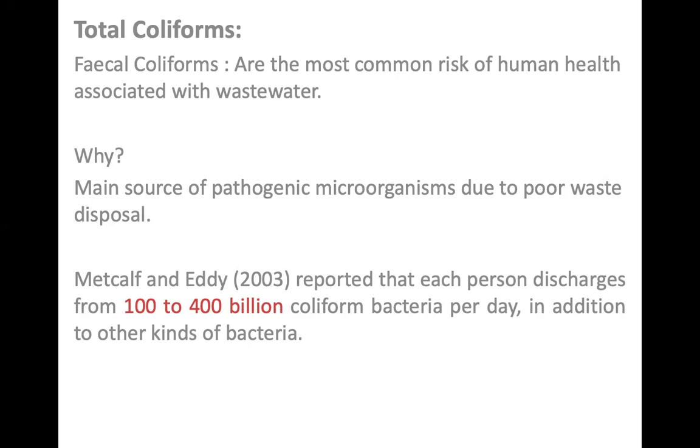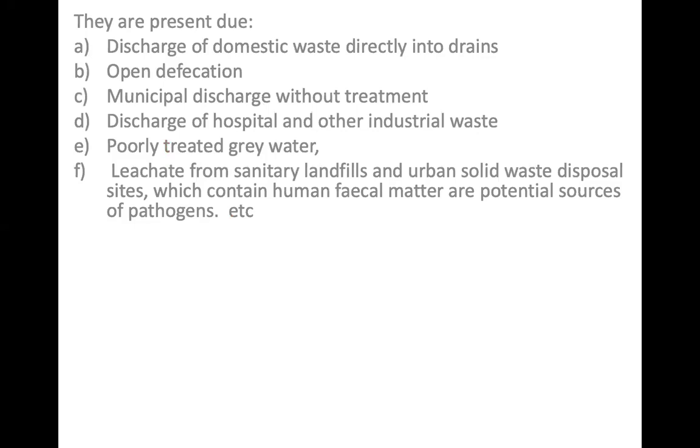This is because according to Metcalf and Eddy, in research conducted some 20 years ago, human beings discharge close to 4 billion coliform bacteria per day, in addition to other kinds of bacteria. And so looking at the number of living human beings that we have, and the discharge that we normally do, it means water can be polluted with this and they must be detected. Now, the main reason why we normally use the total coliform in determining the quality of water is that we cannot practically look at the individual organisms.